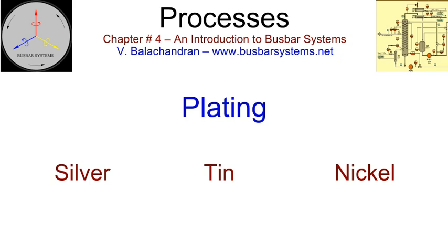Most of the busbar joints will be installed at the site. There is a significant time interval between the dispatch from the factory and its assembly at the site before commissioning. In many sites, the bus products are stored outdoors and exposed to the elements. Hence, all plated contact surfaces of the busbars of a factory-assembled section must be thoroughly cleaned and a protective cover wrapped, to prevent surface deterioration due to oxidation and corrosion during the intervening time.